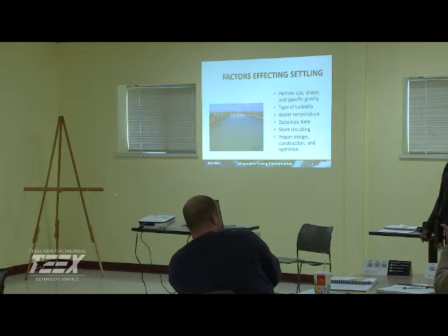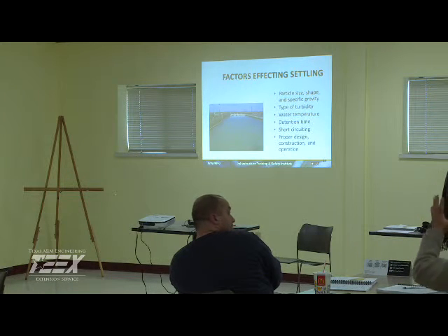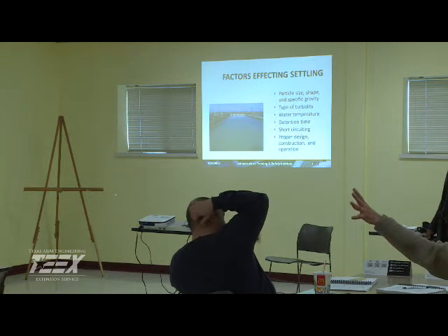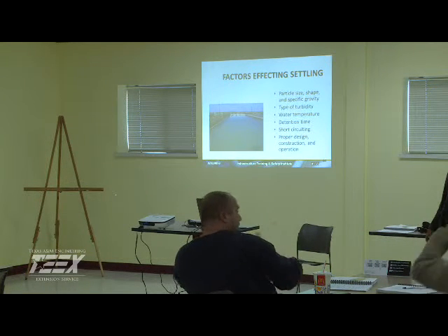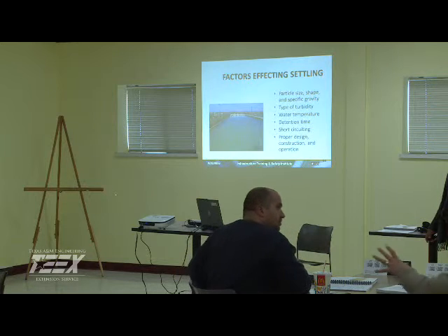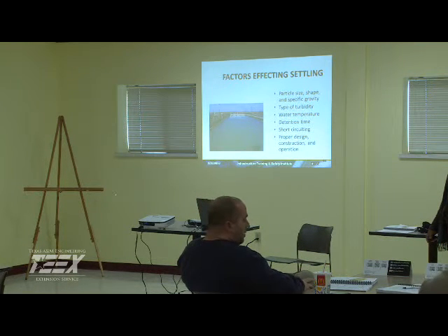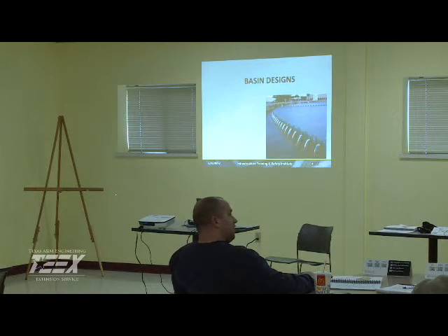A good example, Shane, is the raw water tank at South Wellfield. There are baffles in there, and the reason is that it forces the water to go around the tank. If there weren't any baffles, the water in the back of the tank would just stay there and wouldn't circulate. So they designed it so the water has to go this way to get back over to the intake for those pumps. Excellent example. The front tank's not like that, is it? No, it's not baffled. It could be, but that's high velocity in that tank.